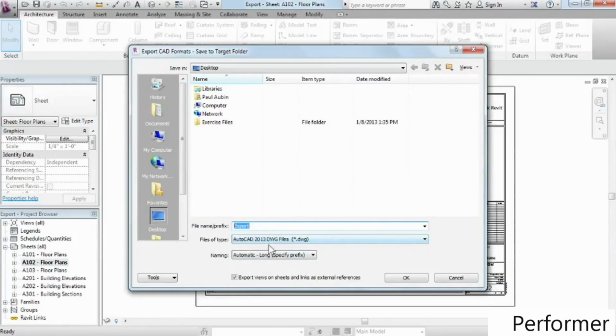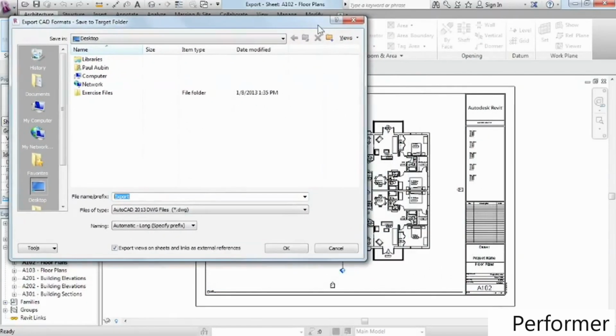And then this setting here is a really neat setting. If I move this dialog kind of out of the way a little bit, in the background, I've got a title block sheet with a viewport on it. Down here, I have elevations and section sheets that I'm also exporting, and those also have viewports on it. What this feature does is it creates one DWG for the sheet itself, sets it up in Paperspace, and then it creates a separate DWG for each viewport, and it XREFs those in and puts them on the sheet. Really nice because that pretty much matches exactly the way that an AutoCAD user would set it up.